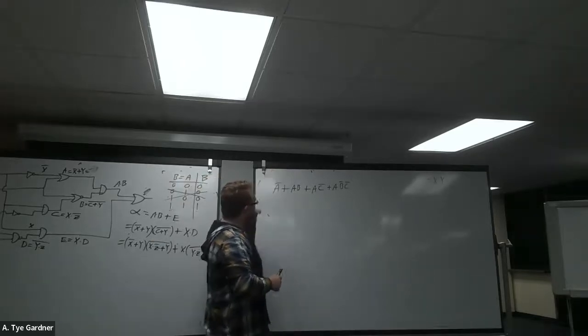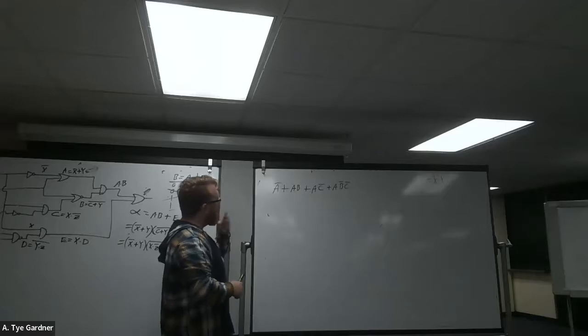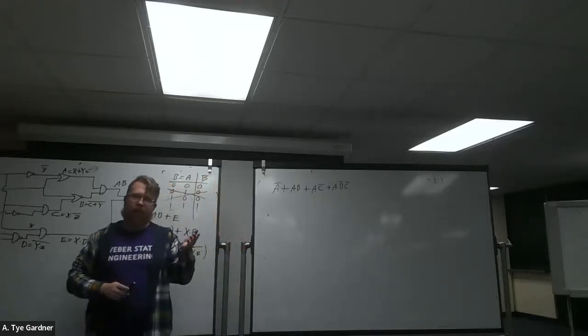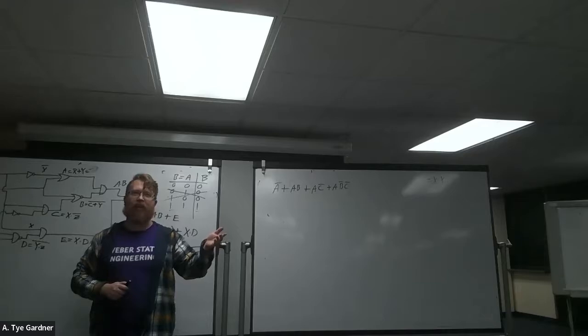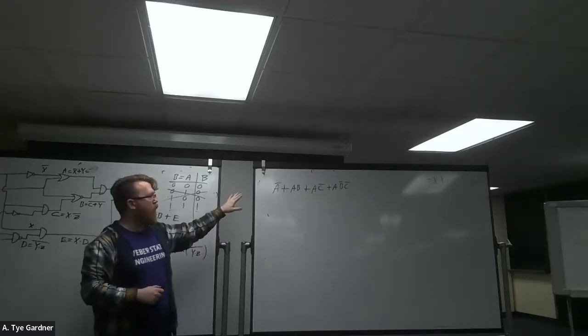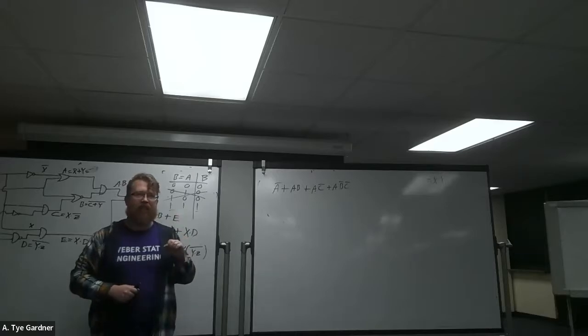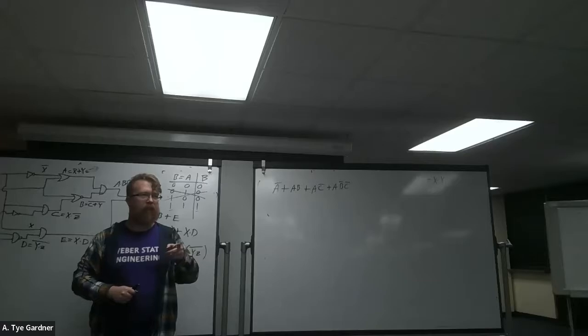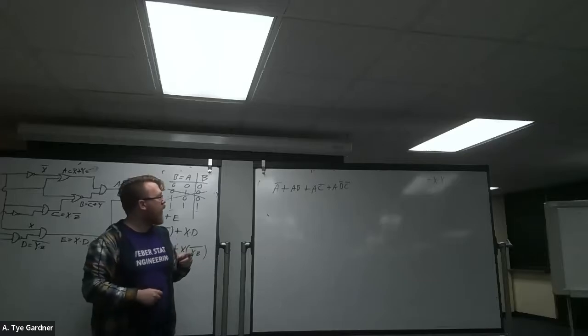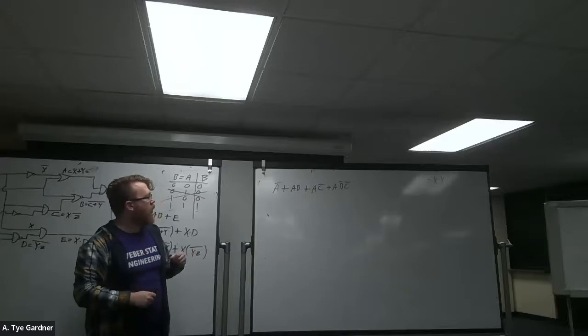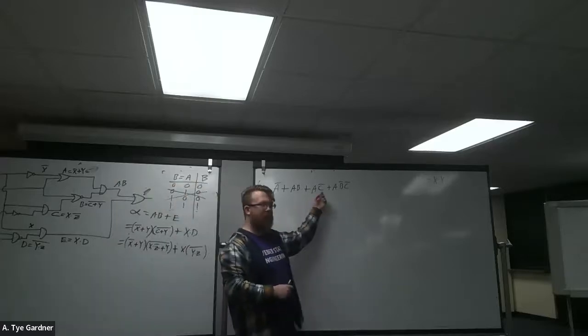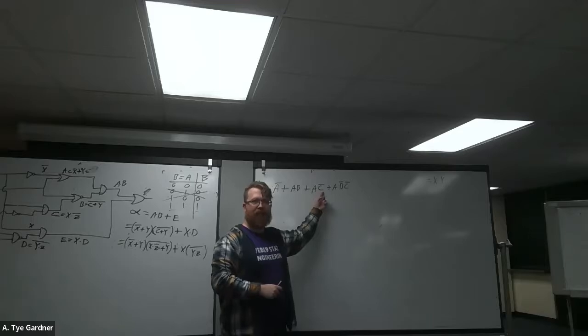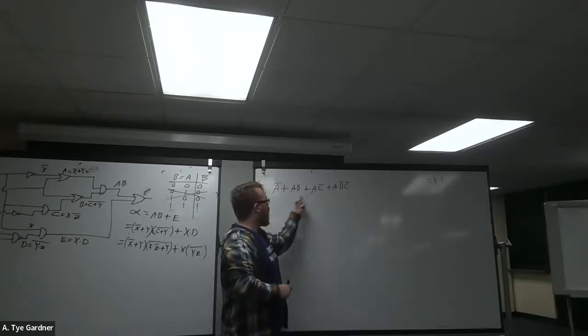But it's hard. Does anyone see the difficult to see simplification that I have? There's something that we can simplify up here, but it's more difficult to see than factoring the A. Yeah. Can you factor not C out of like the A not C and A not B not C? Yes, you could absolutely factor out that C bar, and that one is probably actually a better one, right? I actually like that simplification better than factoring out the A.